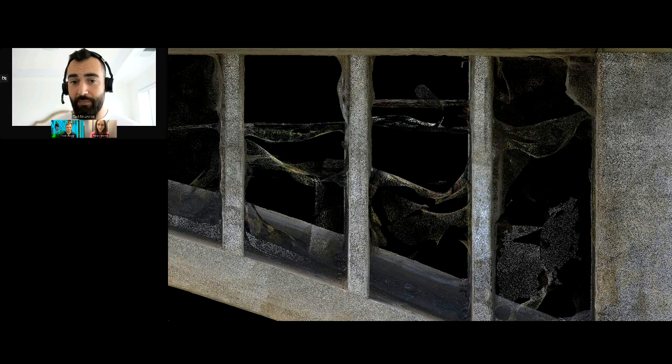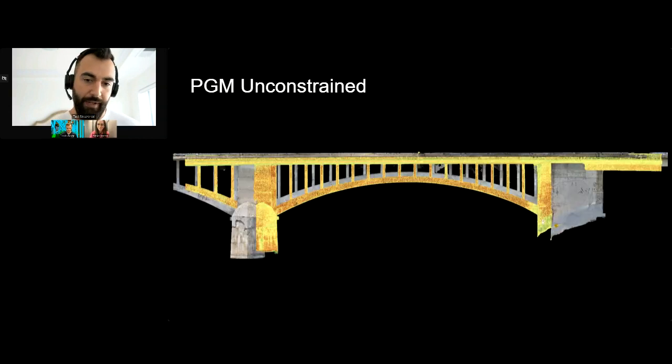And photogrammetry isn't perfect either. Even though the drone was able to see areas where the laser scanner may not have been able to see, we never put the drone through the bridge to capture these images and create the model. We're very interested in the exterior for this quick scan. And this quick scan was about 3 hours. It was at the end of the day. We had already done most of the inspection, and it was just sort of a test for us. So you can see some of the deformities in that interior section.